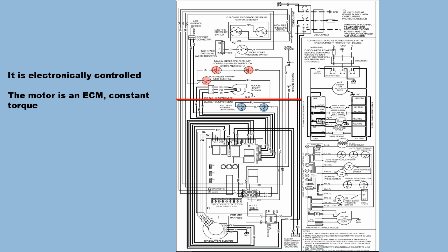And then you have modulating now, from like modulating equipment. If you've got a gas furnace that modulates from anywhere between 50 and 100%, then that motor's got to go up and down according to the percentage of the gas that's being used. If we're only operating at 55%, well, the blower speed's got to slow down to keep a constant temperature rise for that 55%, or to wherever it modulates to.